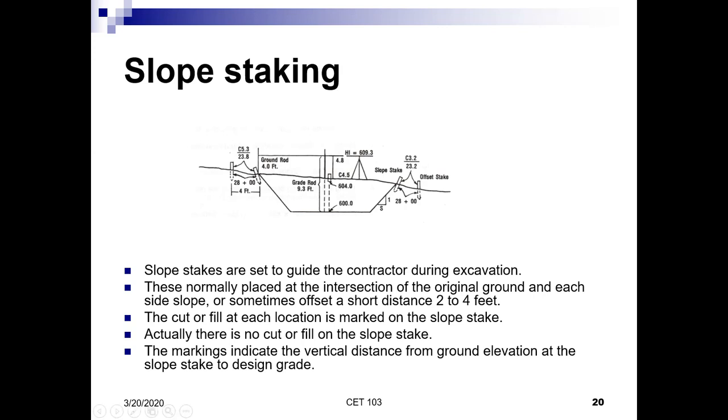So in this sketch above, you will notice that right here, there's a stake set. And let me explain to you a little bit about this sketch. This line that you see that runs across here is the existing ground, while the line that you see here that's very rigid and straight would be the proposed area to be cut. In this situation, it's a cutaway section. It's a cut section because the existing ground sits higher than the finished ground.